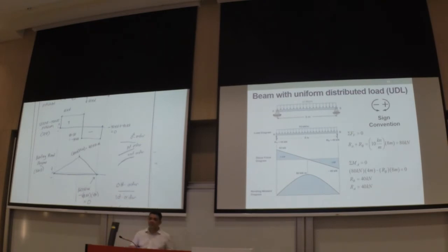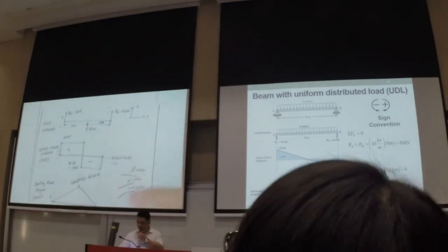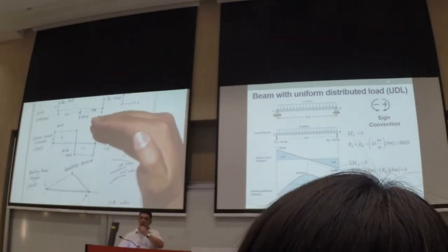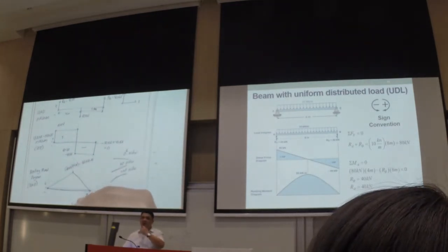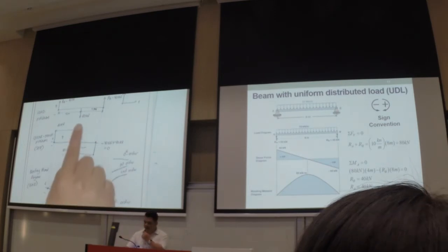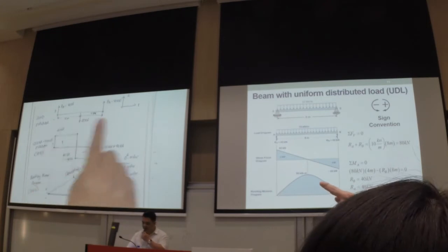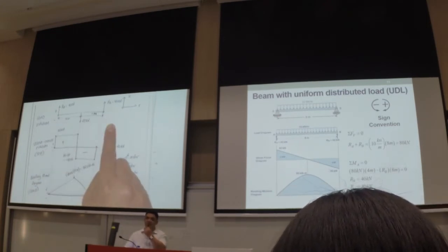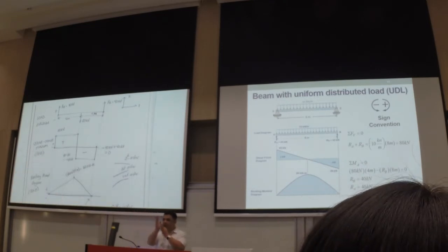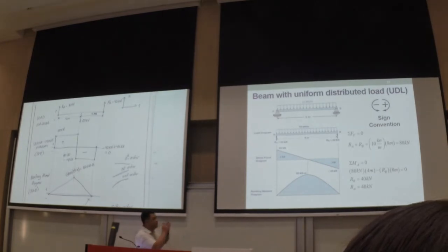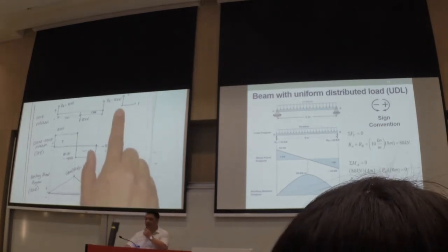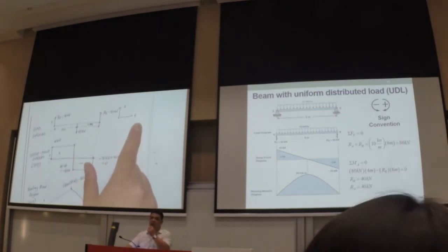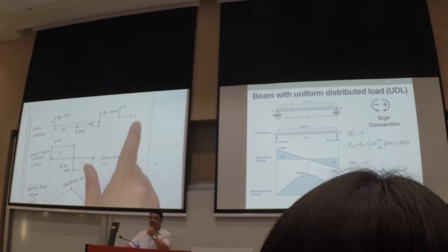So a few things to consider. May I have your attention now, please. Right, a few things to consider. If we're doing the shear force and the moment diagram, we go by order. If this one is a zero order in the load, your shear force will be first order and this one becomes second. At the moment it's just a simple point load, meaning that we just have 80 kilonewtons there and then we have the reaction forces at the ends. We're moving from left to right. Why? Because our axis is from left to right.